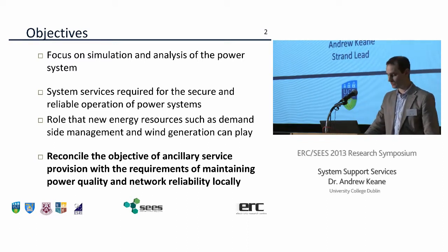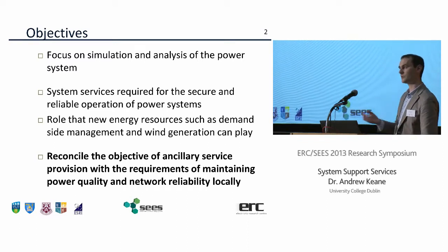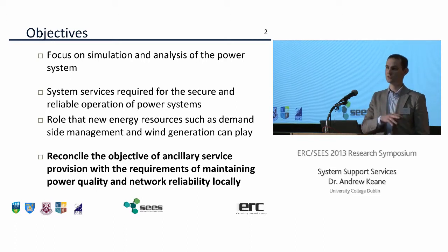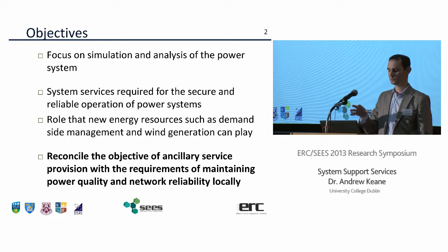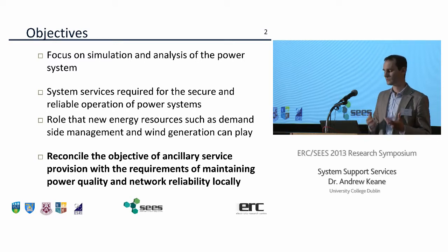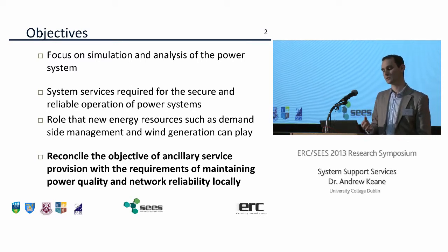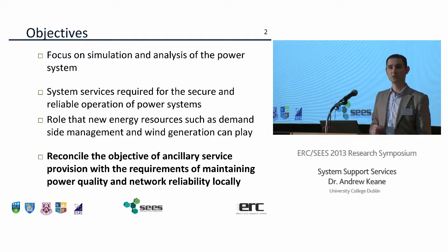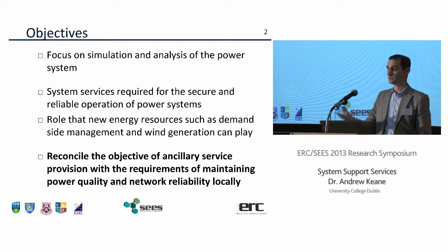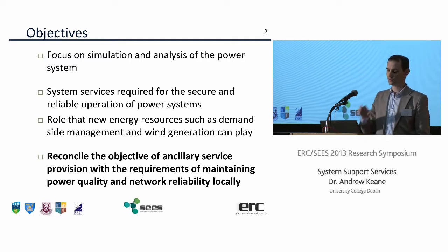So system analysis, and what we mean by that: our focus within the strand is really on simulation and analysis of the power system. So on the generation side and on the demand side, and also particularly on the network infrastructure itself, what ties the whole power system together. A particular focus for us at the moment is around system services, the services that are required for the secure and reliable operation of the power system: reactive power, reserve, frequency regulation, things like inertial response. So we're trying to address these.